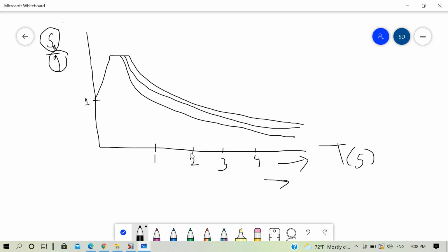So when modal analysis is performed for our building, we get different modes of vibration, and the number of modes of vibration is dependent on the number of degrees of freedom in our building. And we also know that each mode of vibration is associated with a particular natural frequency or a particular time period. We saw in our previous lecture that the lower modes have the higher time period, and generally for shorter buildings or buildings of lesser height, only the lower few modes contribute to the total response of the building, and the higher modes are generally negligible.